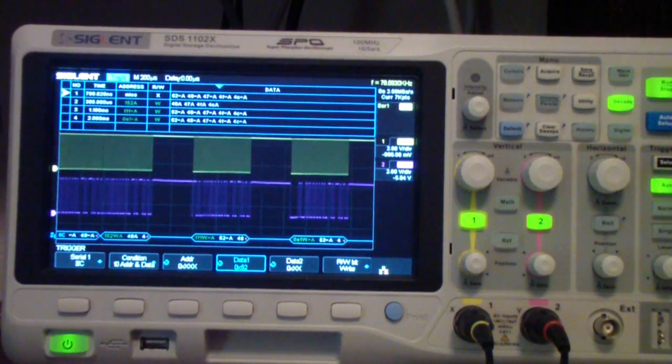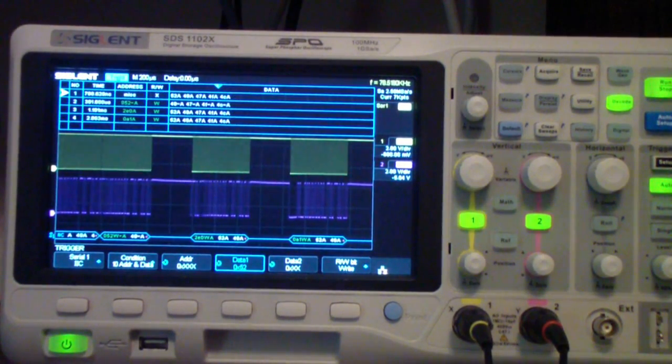I've now set up the Siglent SDS1000 to decode an I2C or an IIC bus. Once again, the data that's being sent is Rigol, and I'm not going to go through the setup on the Siglent because, as you'll see, I really don't consider the decode in the Siglent to be adequate if you're actually working with buses. In other words, it's somewhere between a toy and something you can use, but it does not decode into ASCII or any other format.